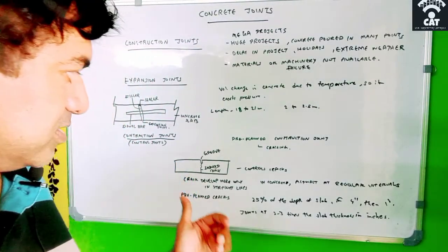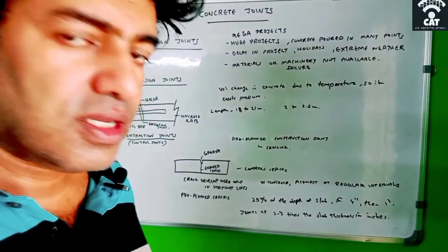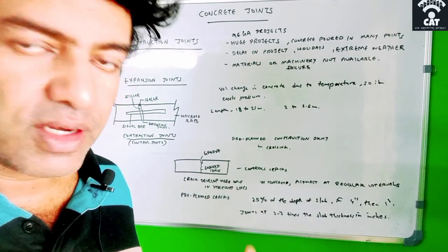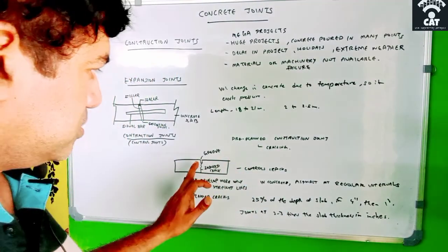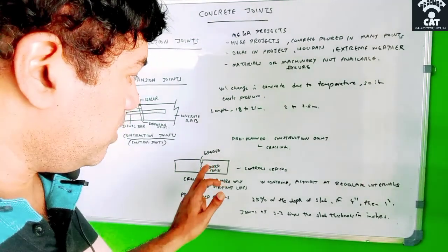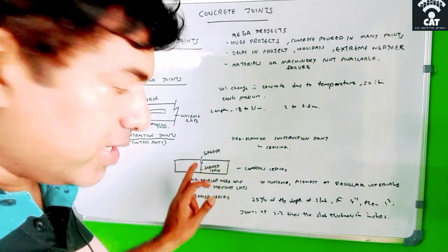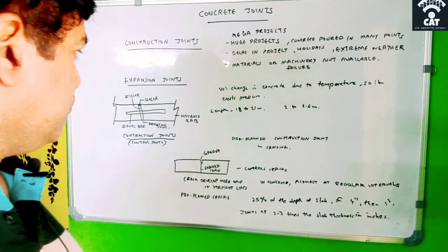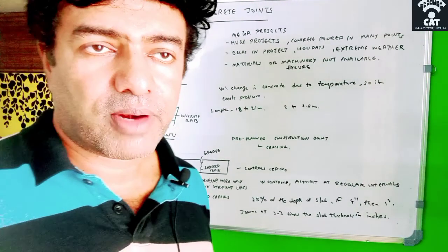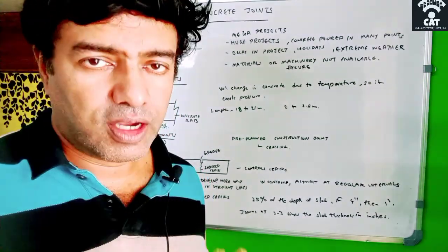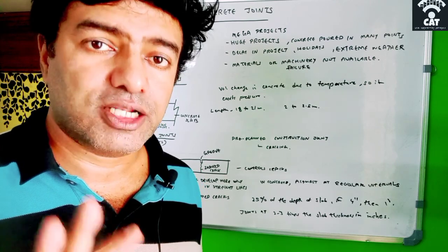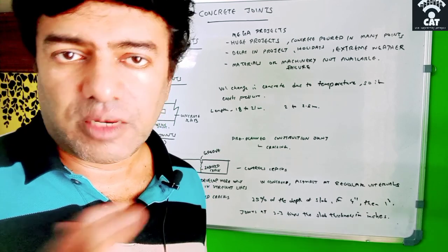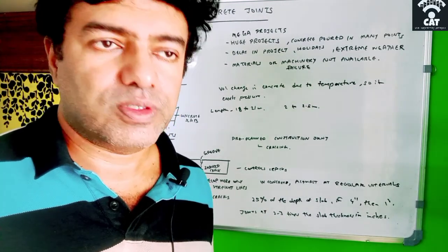We can see that in concrete roads also, because a lot of loads come on the road, and the force will distribute in such a way that it will break at these grooves. Because there is a gap for this groove, it will break there. If there is no gap, it will break the whole slab area or road area. So this is pre-planned crack formation in the concrete, called the contraction joint, which will help to avoid further cracks in that particular concrete or asphalt region.